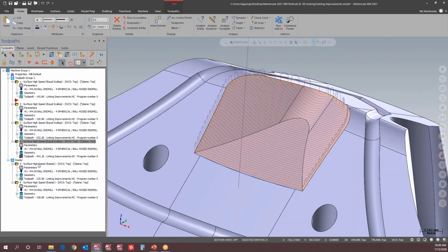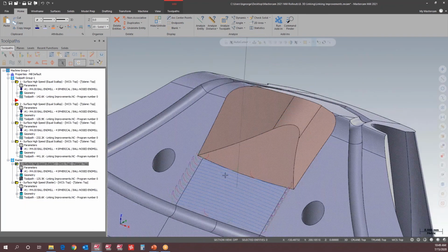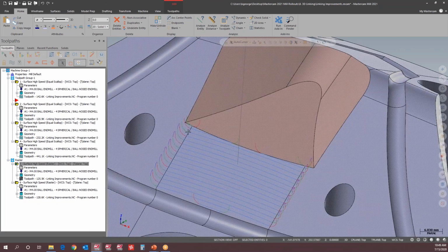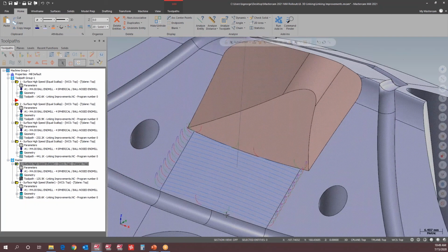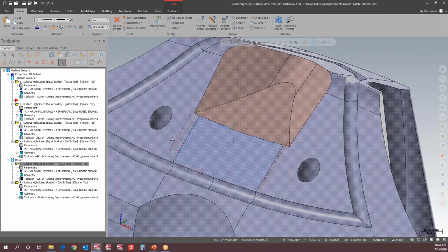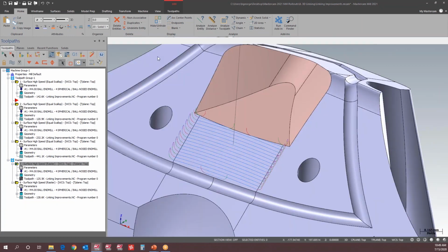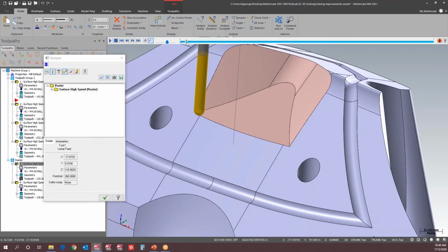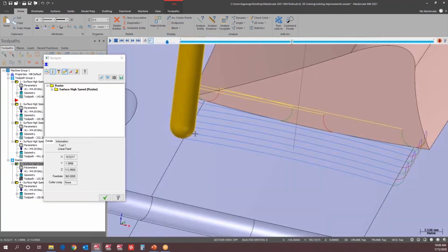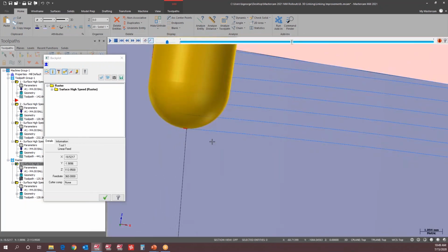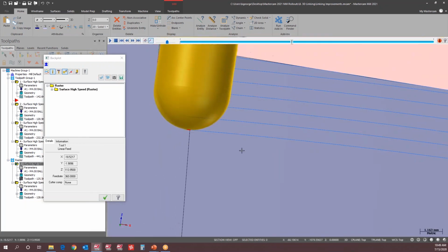Now let's take a look at what the extension one means. Say I have this shallower piece of land here that I want to do a raster on. Before, I think I have my apply transitions on still, but what's happening is our tool stops right at the section of this surface.